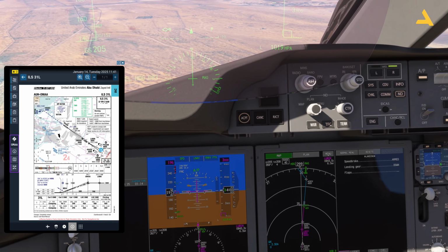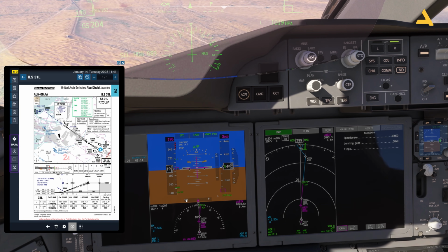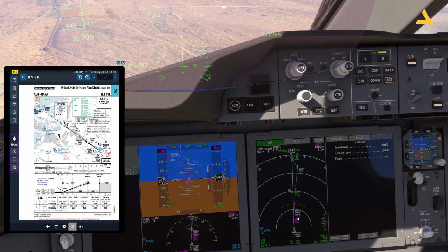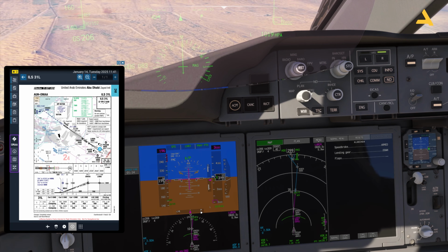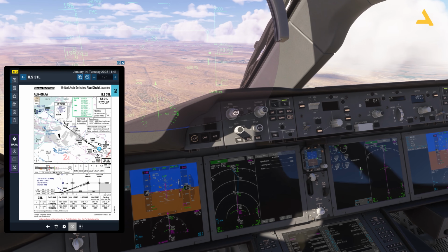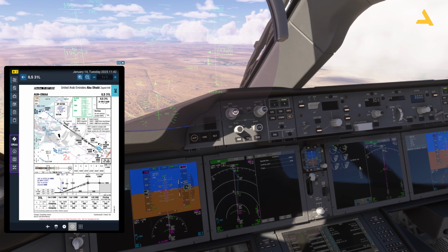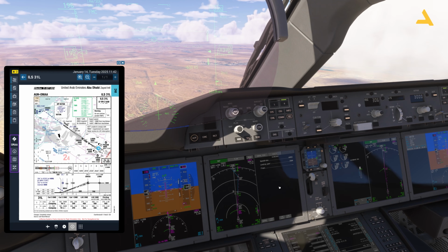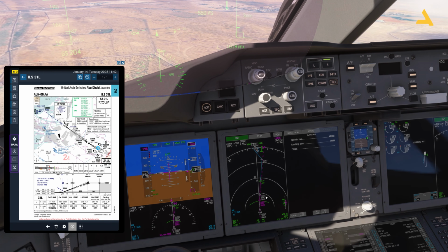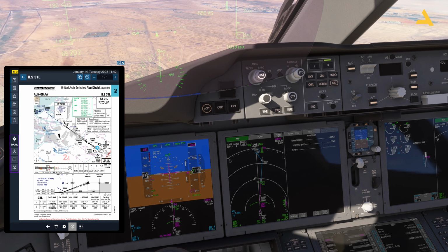And now you can see the diamonds have started to appear for the ILS. So this is for the glide slope, or for the vertical path, and this is for the localizer alignment. Right now just only one left turn is required, and then the plane will be aligned with the runway. And with this also adjust the heading. So you can set the heading button to 306. That's it. Now I can further extend the flaps. Set to 10 degrees.